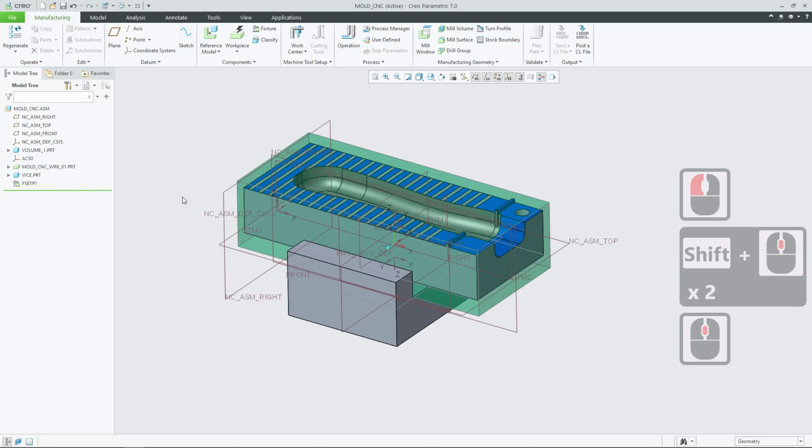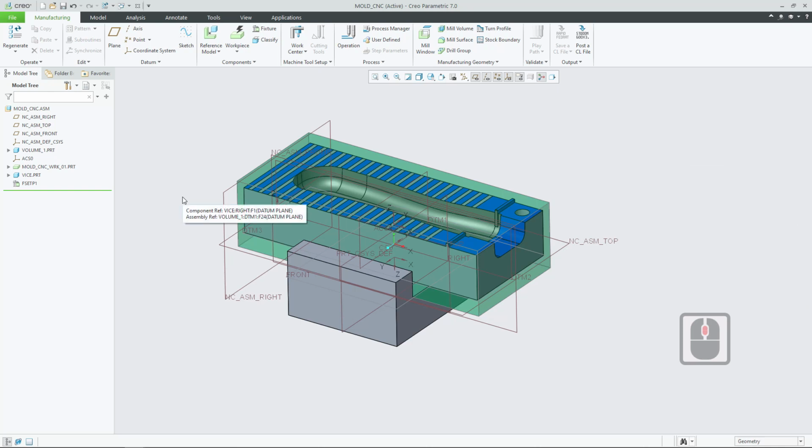The next thing that we're going to do, before we actually go on to create some milling sequences themselves, is create a coordinate system for all our machining operations. This is often referred to as the 0 point or the origin point, and all CNC machining requires the definition of where this 0 point will be.